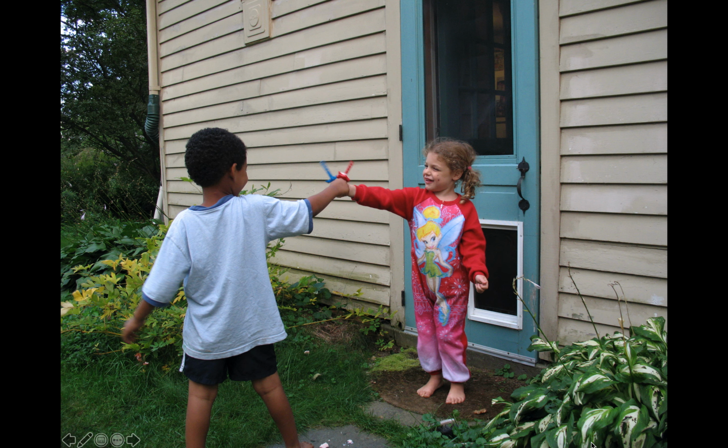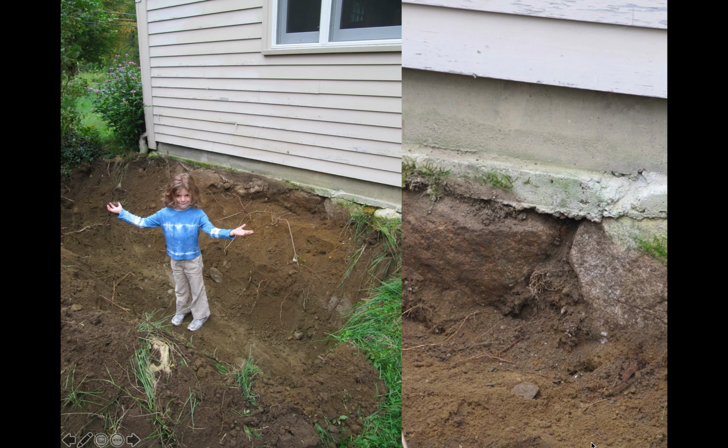But like I said, it was quite pleasant. Kids were having fun. Pay no attention to the rotting clapboards and door frame in the background. That's of course not important. Actually, it was terribly important, and I realized I needed to do something about it, and it needed to be a lot bigger than the small moves that I had been making so far. So I decided to install a drainage system and what I called wing insulation, essentially an underground insulated roof that was going to guide water away from the house and also insulate the floors.